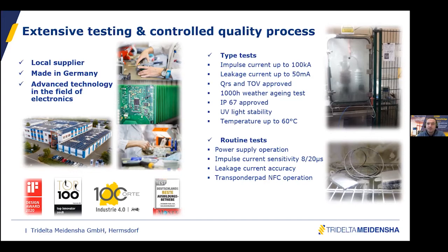And then, of course, a lot of type tests have been performed on the product before the official sales release in 2019, to make sure that the smartCOUNT can withstand the same duty, the same stress as the surge arrester. For example, the charge transfer, the TOV capability, the weathering test.